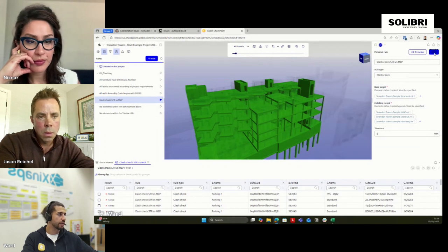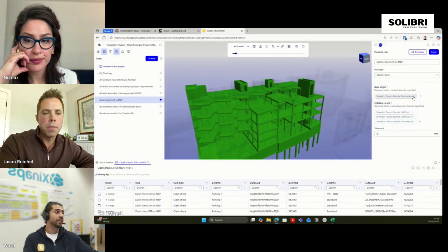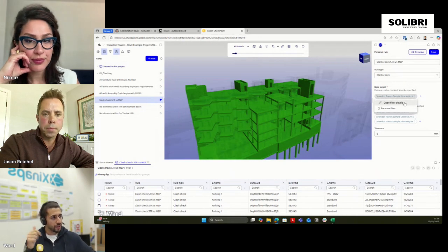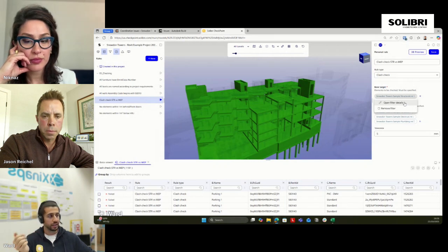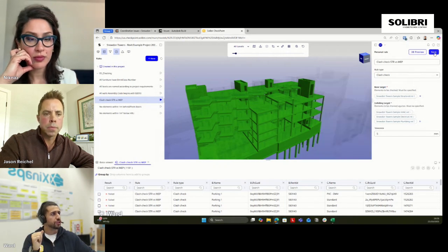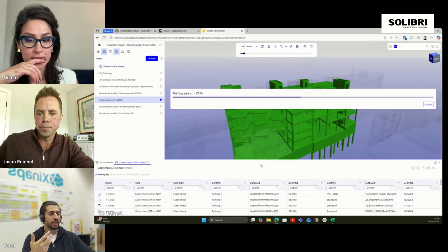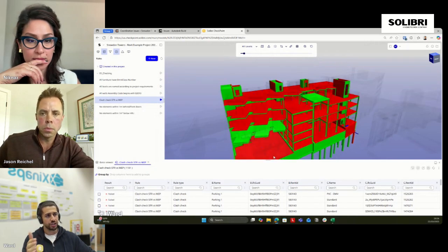Okay, so you're filtering out those areas or spaces. Exactly, because also when using other tools, the areas might be an issue. It's a Revit category, basically. So there needs to be a way to filter it out from the model, and this is what I did. I just provided a statement over here to remove the areas from the structural model, so I can have more reliable clashes between the structural elements and also the MEP.